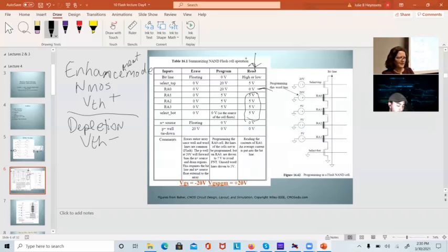So instead of metal oxide semiconductor, it was metal epi-layer semiconductor, and they had better frequency response, so they could amplify at 1 gigahertz. The drawback to them is they were depletion mode devices. So if you did not actively put a negative voltage on the gate before the other voltages came up, it would blow craters into these poor little devices.